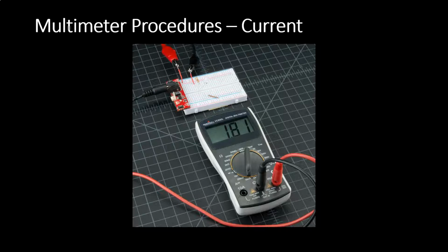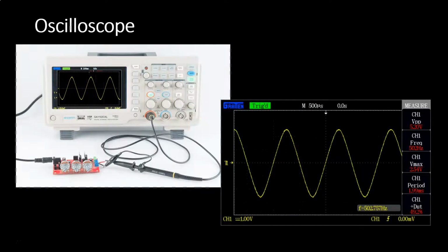The current sensing is actually one of the strangest measurements with the meter, and in this case you basically connect the meter in series with the thing that you're measuring the current of, but you have to make sure you don't exceed the limits of the meter, because some meters can only handle 1 amp. Some meters can handle more than 1 amp. In this case, this meter can actually handle up to 10 amps, but you would need to move the red lead from the right-hand side to the left-hand hole marked as 10A for 10 amps. So you've got to be careful that you don't exceed the working limitations of the meter when you're testing current. But current is connected in series with a circuit, whereas the other measurements, the resistance and the voltage, are measured in parallel.